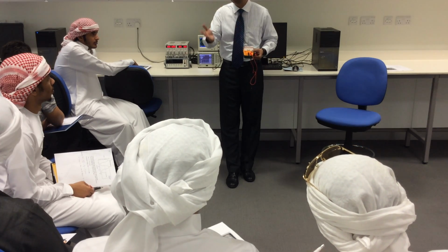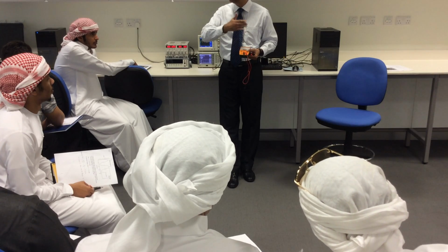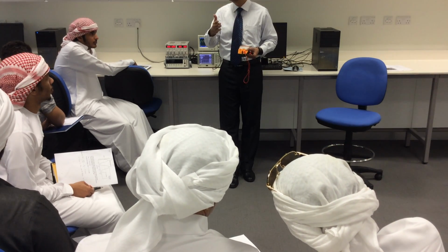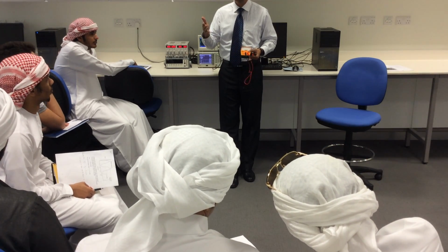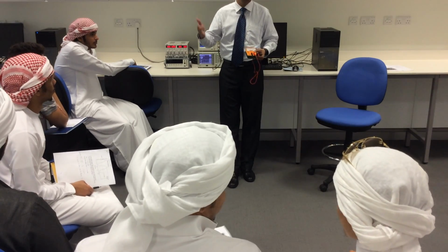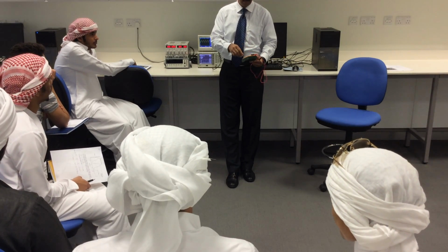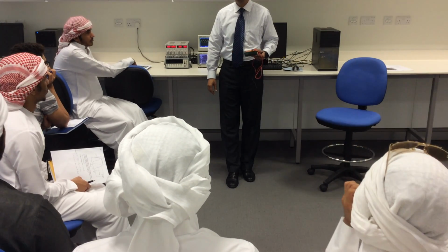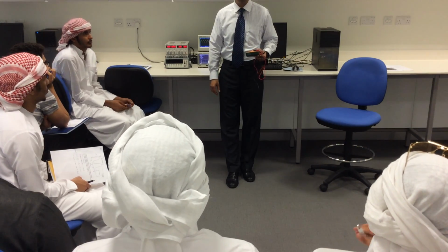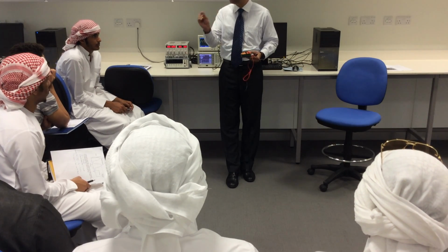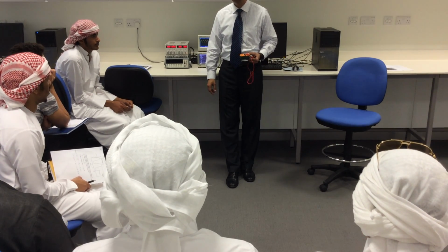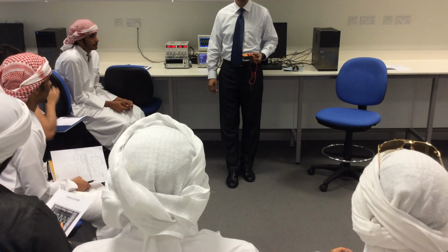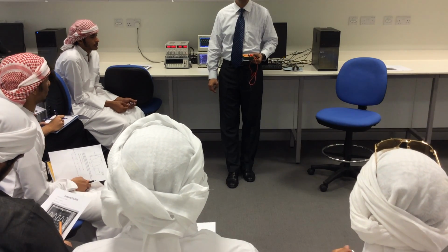If it is 0.3, you will not know. You can measure either 0.2 or 0.4, and then move on. And if you want to measure a precise value, you can select the scale to, for example, 2.5, so it will be 2.5 volts divided by 50. Your steps will be smaller, so you can increase the resolution.